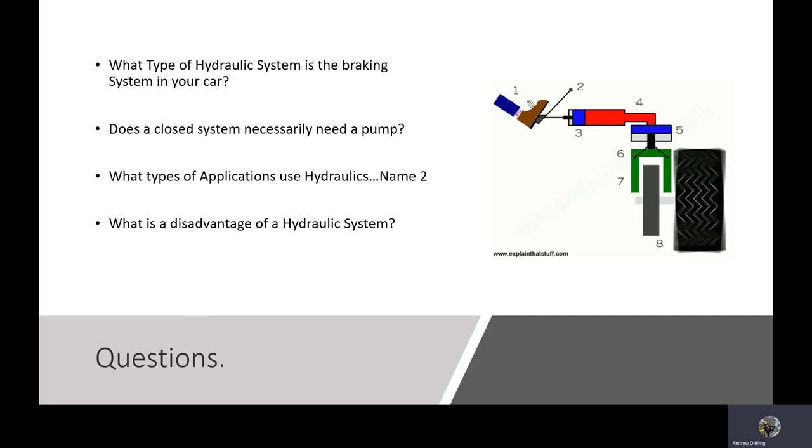But that's more than made up for by the advantages of the hydraulic system, which has infinitely variable speed control. The more or less fluid that I meter through that restriction will affect the speed, but not the pressure. I can also determine the amount of force that I move through it by changing the size of the conductors.